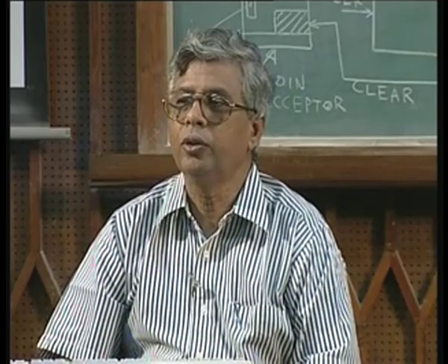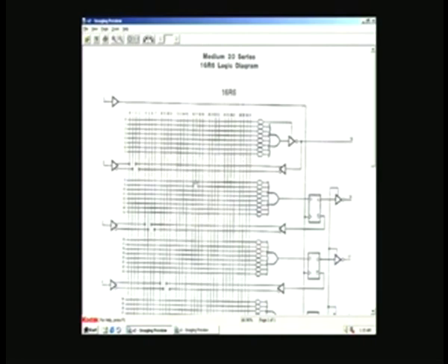The design we have now completed can be fitted into a programmable array logic. The choice of the PAL is important. It needs registered outputs mainly, because all of these are registered outputs. There are states. We know that B, C, D, E, F are all registers, states, and their outputs are also state outputs. So we need registers, and we also need a combinational output, because the clear signal, CCA, requires a combinational output B plus C plus D plus E plus F.